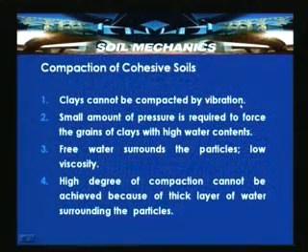And clays cannot be compacted by vibration. We have also seen, by performing a simple experiment in the previous lecture, that clays cannot be compacted by shaking, whereas sand can be made to rearrange into new positions. So, a small amount of pressure is required to force the grains of clays with high water contents.